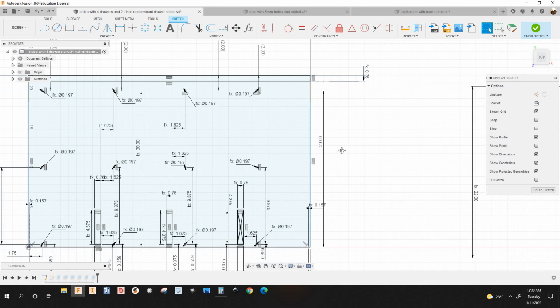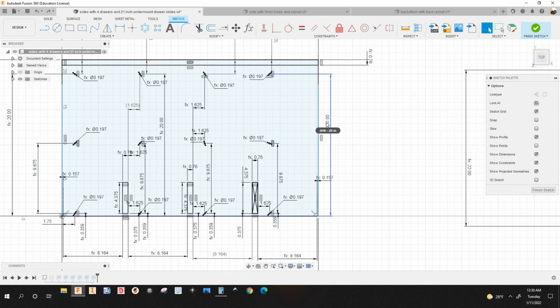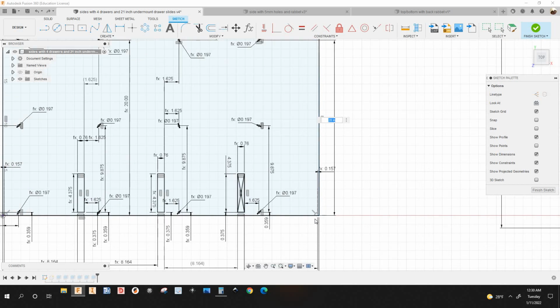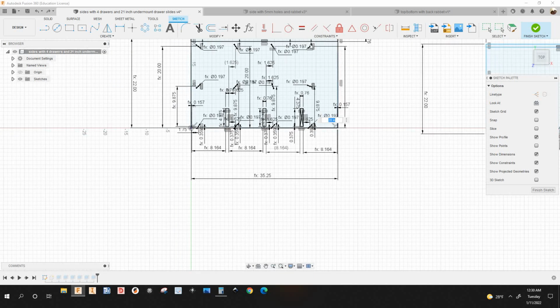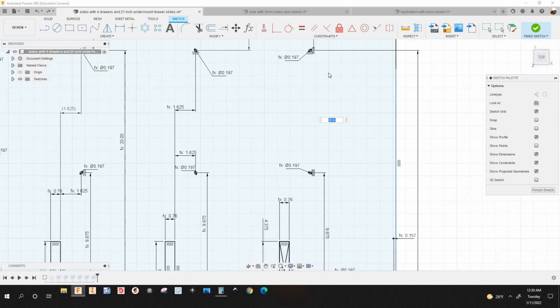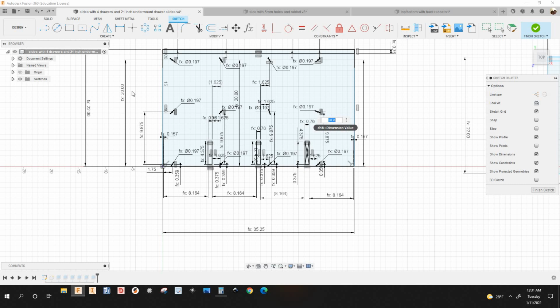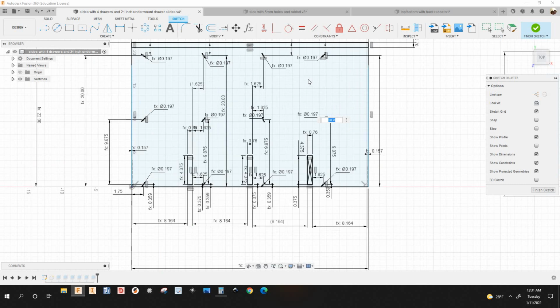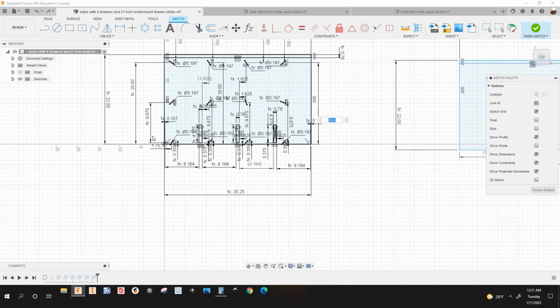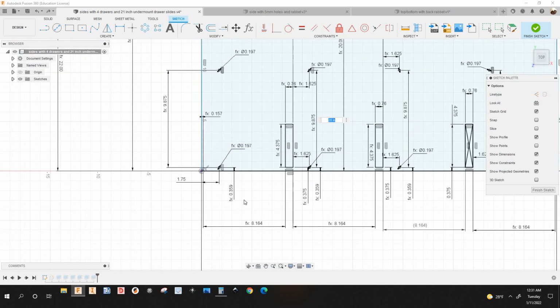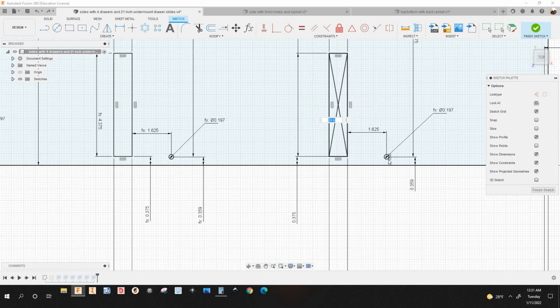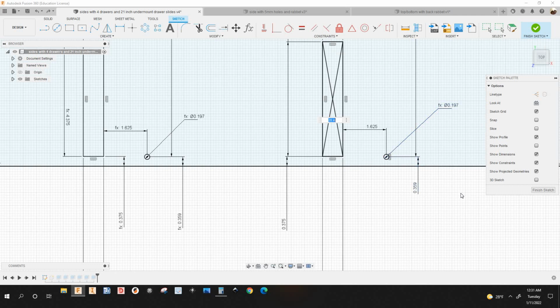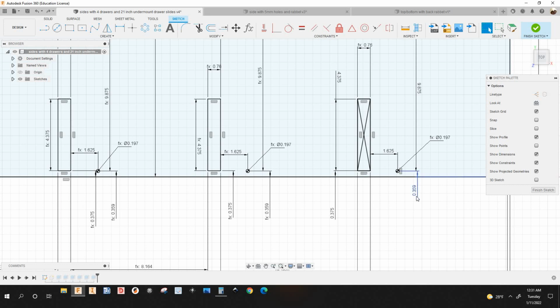See the thickness right here of that rabbet. And see that 20 inches? That distance from this line right here, or this point, to the center of the back hole. That's 20 inches. This is not gonna change when I change the depth of this side panel. And the distance of this hole right here, the first one, it's 0.359 inches.